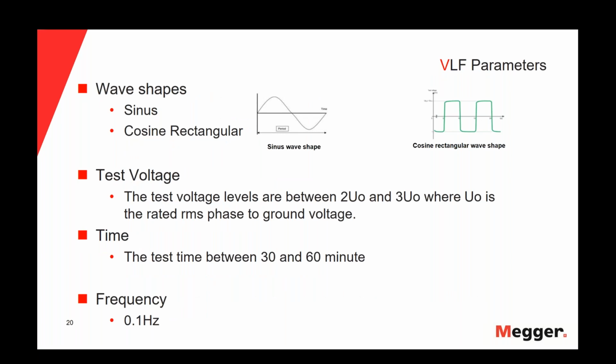So talking about the VLF parameters, we have, of course, the voltage, the wave shape, the time, and the frequency. In terms of the wave shapes, we have two technologies: the sinusoidal wave shape and the cosine rectangular wave shape.